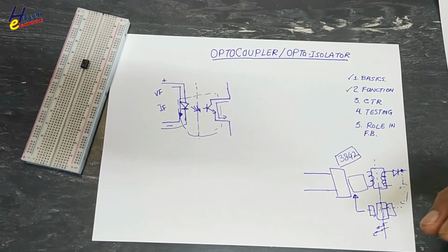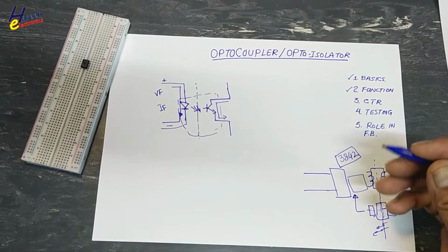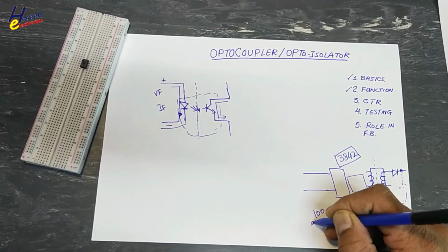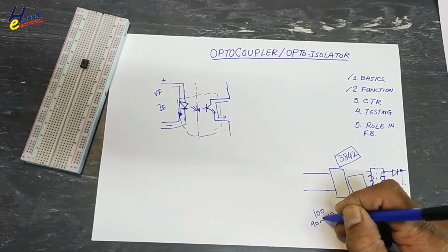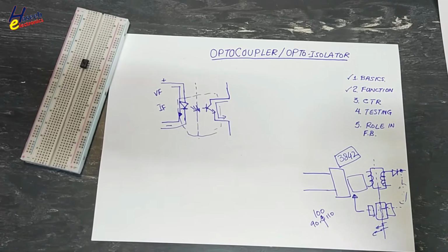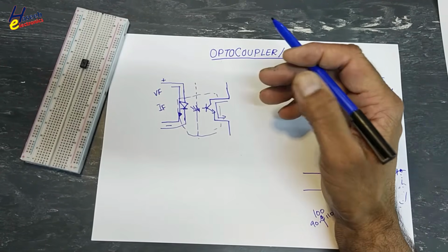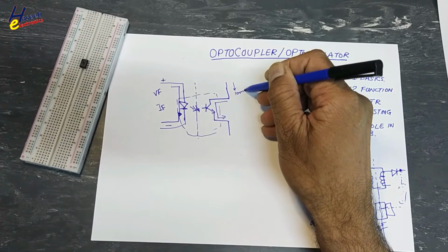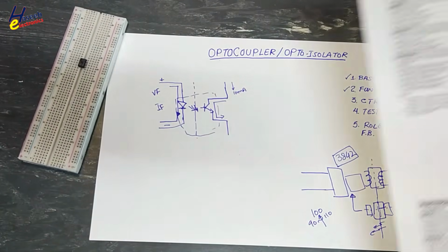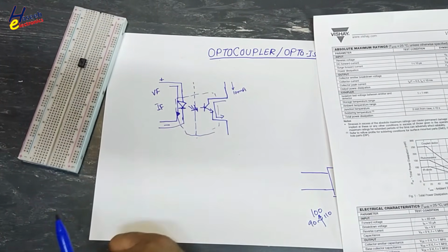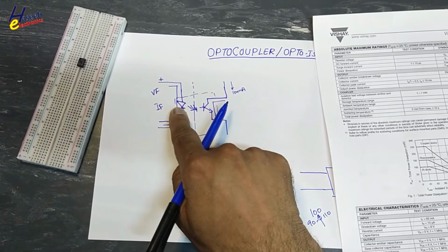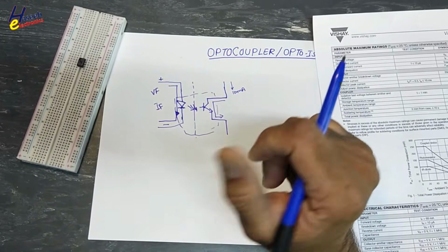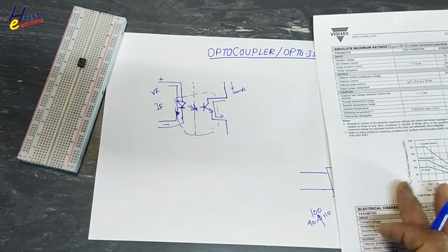In datasheet, in application notes, there is mentioned that 384 series 100 CTR. We can say 90 to 110. Center value 100 CTR is excellent. Let's suppose I need 10 milliampere here in this portion. How much current we will apply here? Because its transmitted light and its conduction are calculated, that are predefined by any manufacturer.